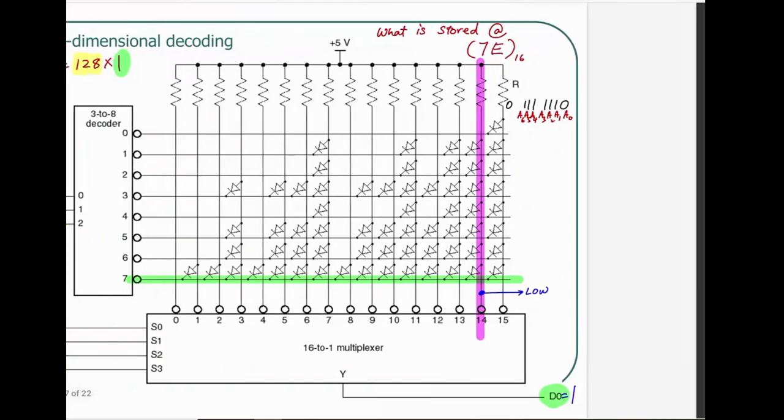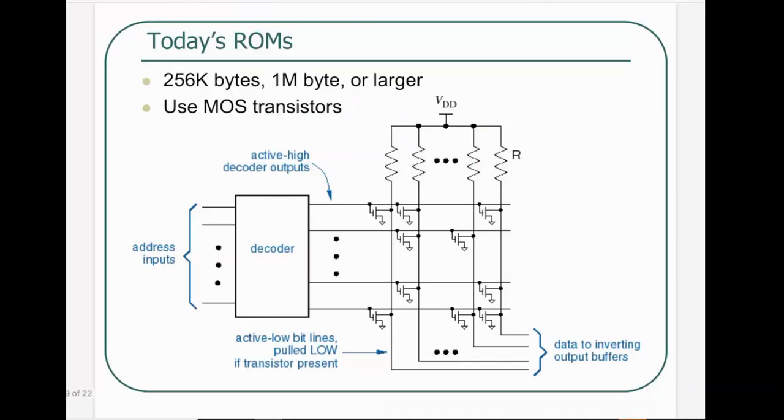So if I come forward over here and say, all right, this is a ROM. What are the inputs to a ROM? An address. What are the outputs from a ROM? Data at that address. So where does the input go? Well, the address inputs go to the decoder. Based on whatever that address is in binary, one of these word lines is going to become active. We could use a 2 to 4 decoder, a 3 to 8 decoder, or a bigger decoder, which opens up our options for the number of word lines to be more and more.